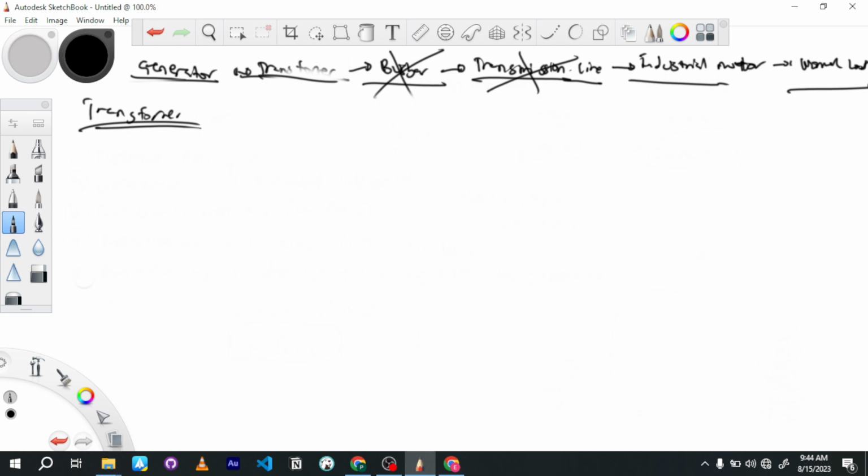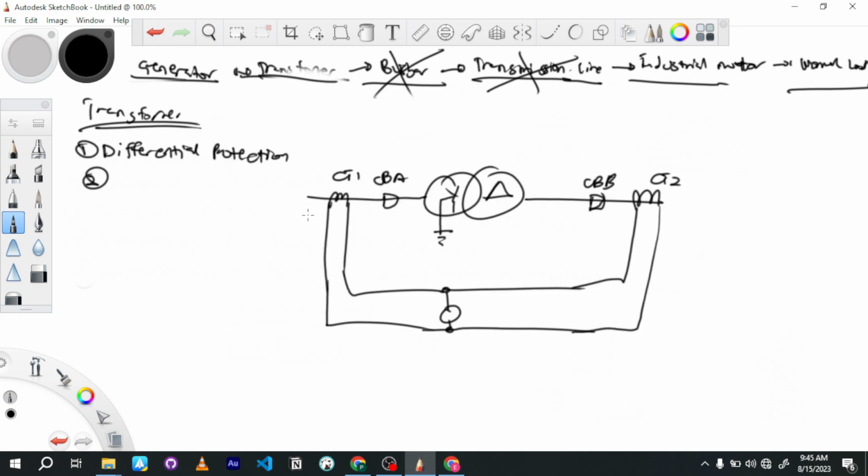There's a question like that I will let us look at, so that even if it doesn't come, it will help you think a certain way. But the main protection is for internal fault, not for external fault. You understand? So this is called the differential protection scheme, the balance current or the circulating current scheme. This is the first one. This helps you against interturn faults, basically.